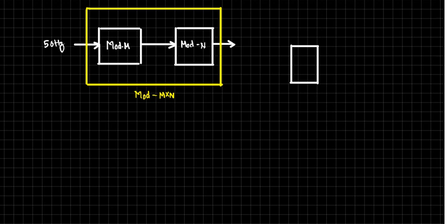That means at the output of this you will get divided by m, at the output of this you will get divided by n, so overall it will be divided by mn, right? So this you should know. I am expecting answers from you guys. Tell me that there is no need to remember this much. Mod m means what? After m, the states will repeat. Now those states will be repeated, isn't it? How many states are getting repeated?